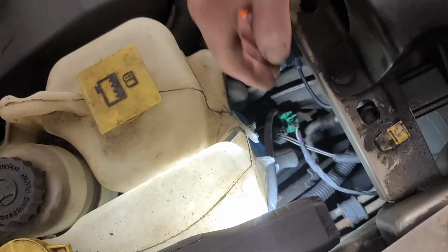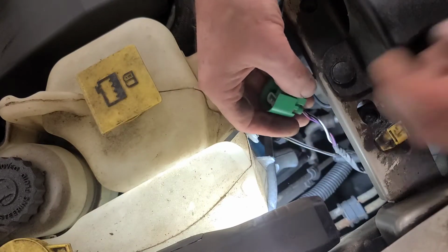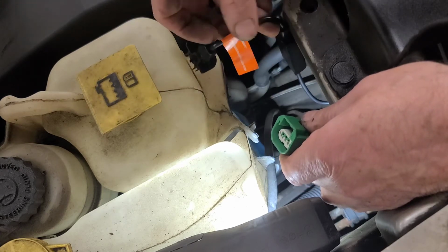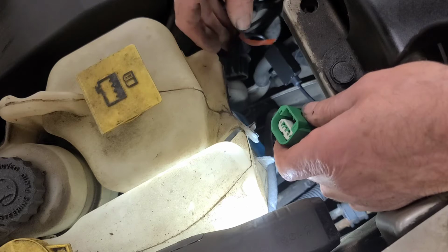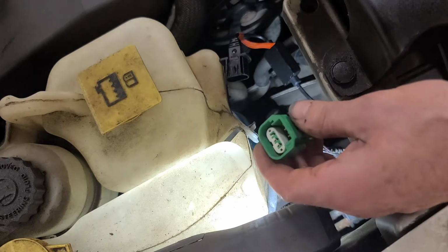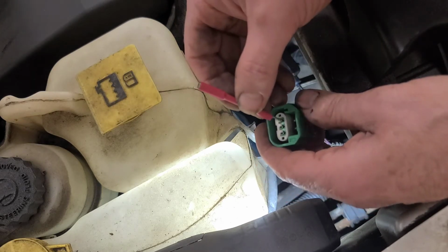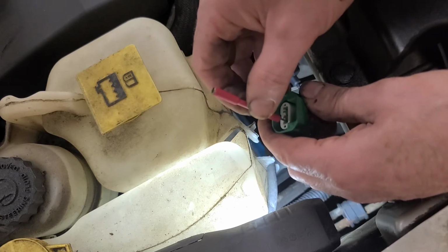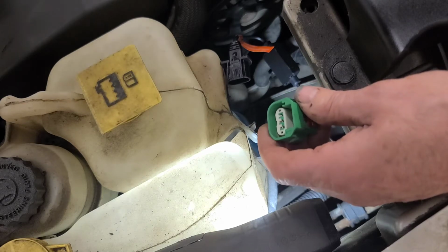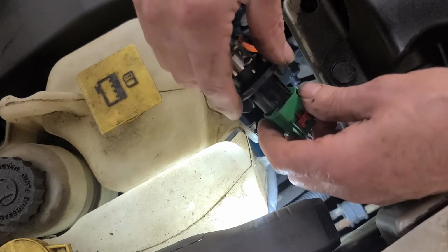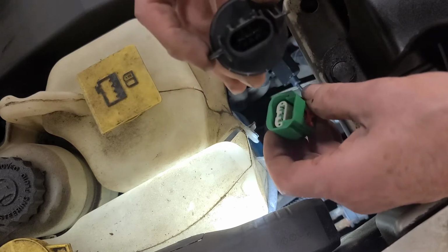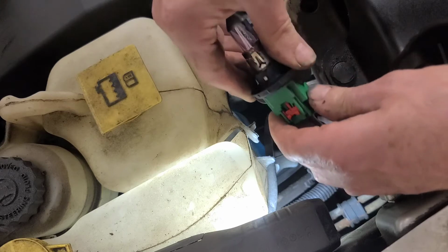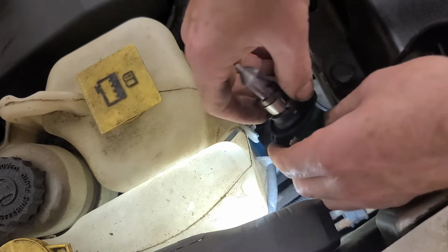So we're at the right headlight assembly, and I've unplugged the aftermarket LED light, which is supposed to be plug and play and have the appropriate resistor in it to mimic the load of the conventional bulb. First thing I want to do is check pin fit, and it feels pretty good. Now, he installed these when it wasn't working, so I'm going to plug in a conventional light bulb and see if it works.